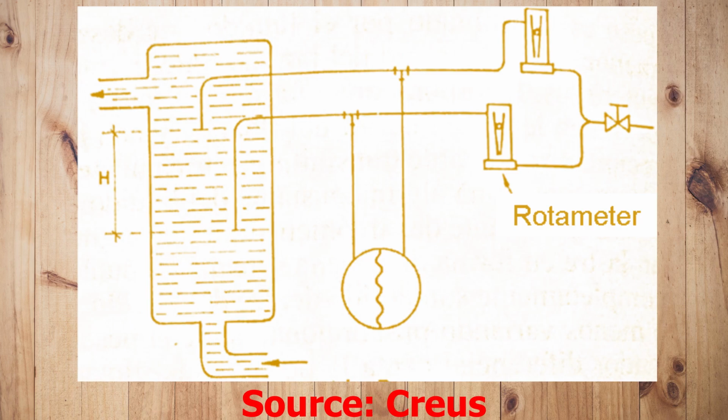In the case of fluids that are not too clean, very viscous or corrosive, there is a risk that the connections to the instrument will become clogged or destroyed. In this case, an air or gas and even liquid purge system can be used through two pipes placed inside the liquid, and whose ends are separated by a fixed distance. In the image above, for the normal installation, the separation would be 1 meter, and the instrument should have a lifting spring set at 80 mm of water column.